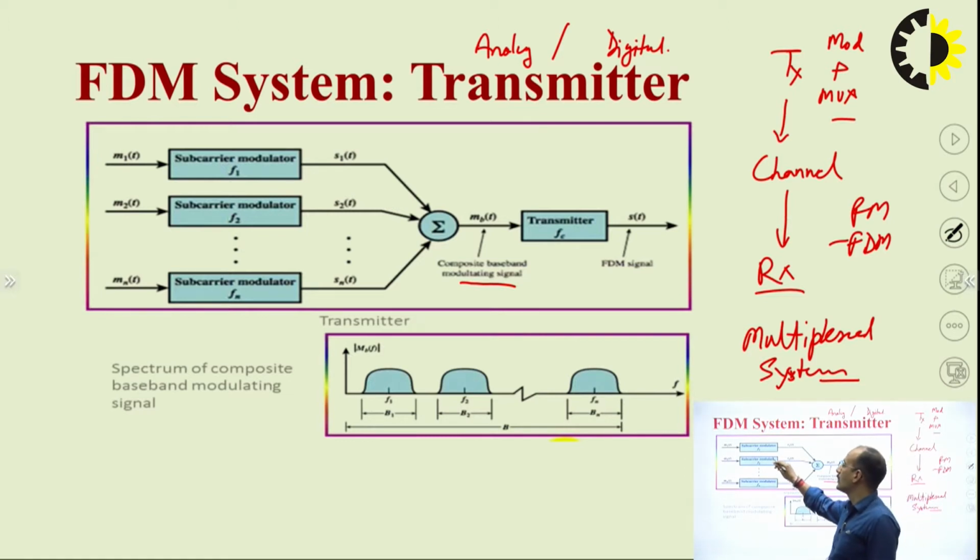We are going to use a subcarrier modulator. Why? In the modulation process, you can also use modulation as a frequency translation procedure. Means, if your frequency lies in the range of f and you want to transfer that frequency into the f1 frequency range, then the simple procedure is just to perform the modulation by using a subcarrier frequency of f1.